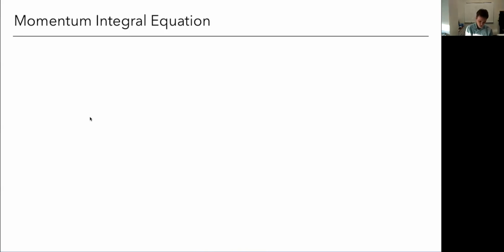Well, we have one new term here, that's H. H is called the shape factor, and it's defined as just a simple ratio. It's not really a new variable per se. It's just a ratio of these two heights that we've seen already, because these two actually grow at different rates for the most part. For a flat plate, they grow at a similar rate, so this actually ends up being a constant. But for a general body, they often grow at a different rate. So H can change along the boundary layer. The reason we call it H, and actually I'm not sure if this is the reason why, but it's convenient, is that it's an indication of the health, so hence the H of the boundary layer.